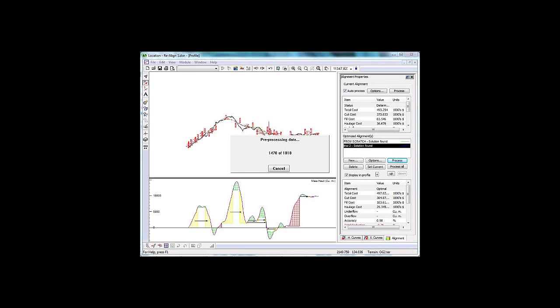He's talking about a bridge. We call those obstructions, and the idea is you can't move material across the bridge until the bridge is finished, so you want to balance your road before and after the bridge. Currently, it's a little difficult to get Softree Optimal to do that. We don't have the option built in, but we have done some research in this area, and it is possible to include that as a feature, and it will be included in the future.